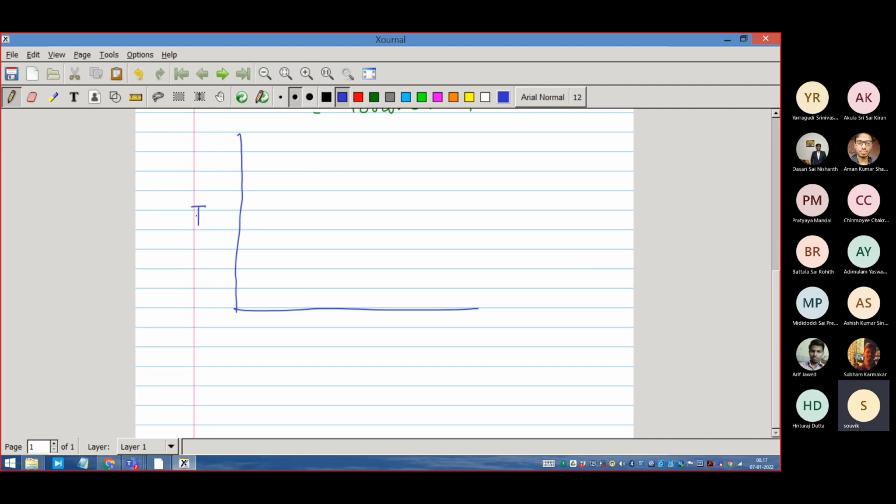We love to look at pressure and flow rate characteristics in their plane. But we want to look at it from the torque developed by the machine and the running speed of the machine in this plane. So this is the torque developed, and the induction machine speed, that is omega rotor. This is the mechanical speed of the machine.